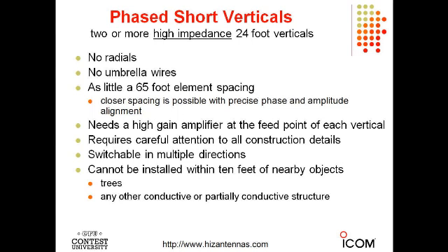He built that antenna before the true potential of these receiving antennas was well understood like it is today. So like most four-square arrays, it was built as a compromise between transmitting performance and receiving performance. You try to achieve both, and you achieve both pretty well, which he's done.